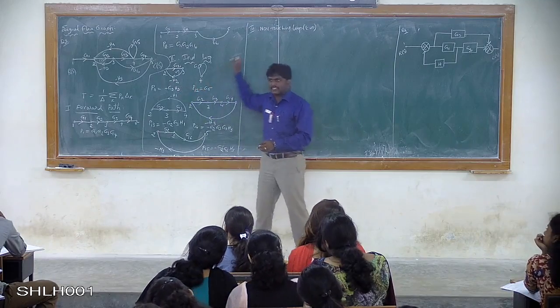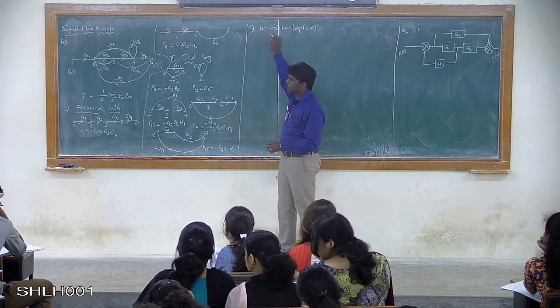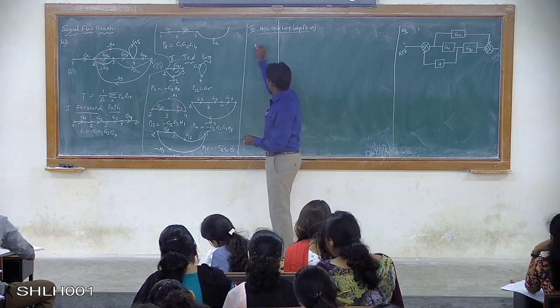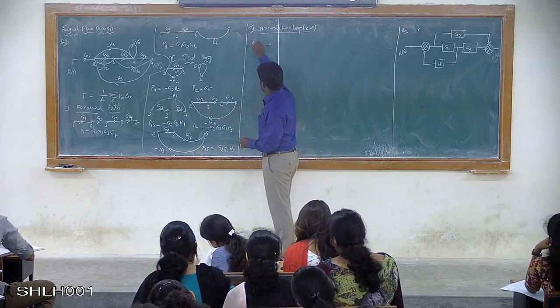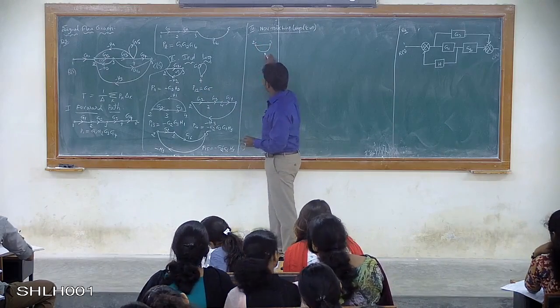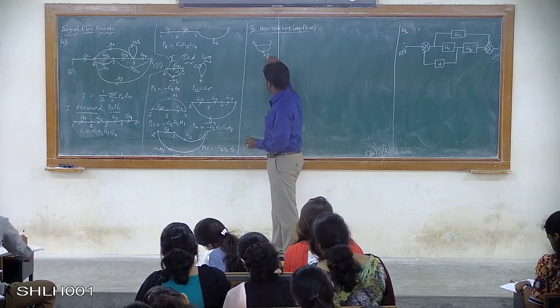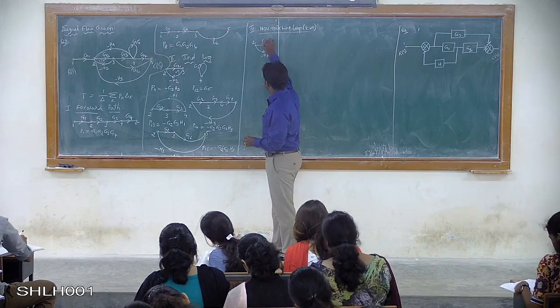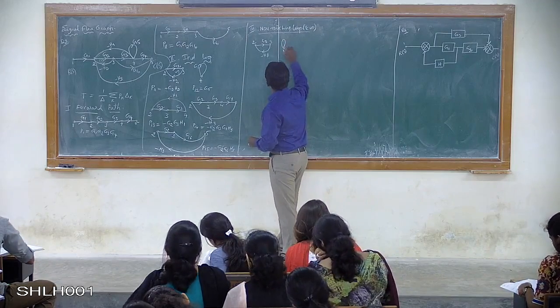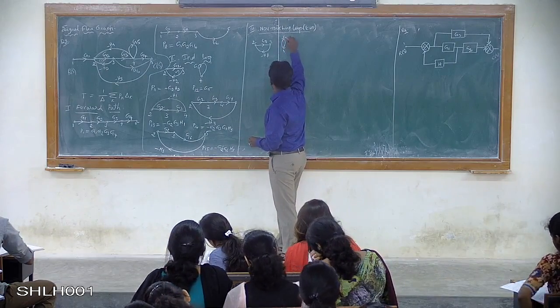So I can take this as one pair of two non-touching loops in the given signal flow graph. So I'm writing the node number 2, 3, then 3 back to 2, the gain value is minus H2, and this gain value is G2, and another loop with the node number 4, the gain value in that is G5.